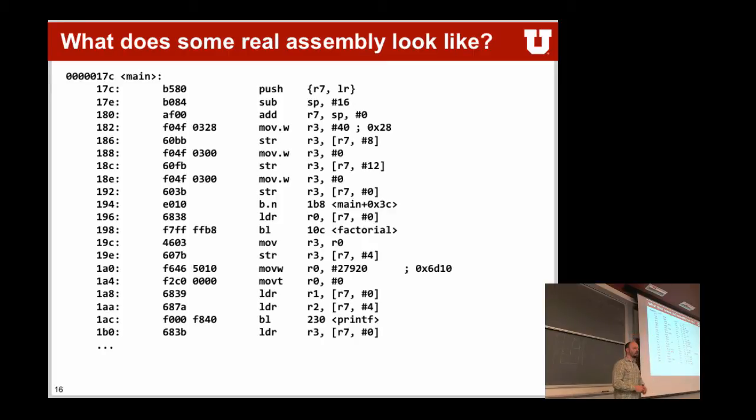We will talk about the stack a little bit later, but basically the stack is where the stack pointer is pointing to. Remember, in one of the registers, the SP, the stack pointer will point somewhere into RAM, and that's your stack. And the push, all it will do is take these two registers and store them into the address where the stack pointer is pointing to.